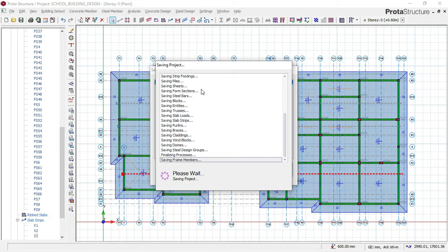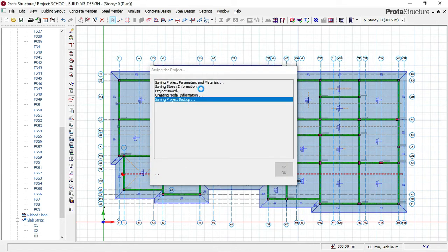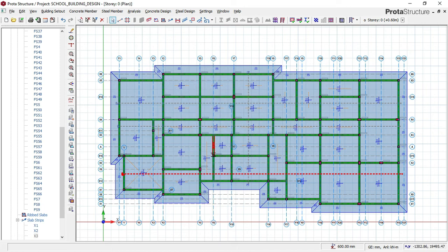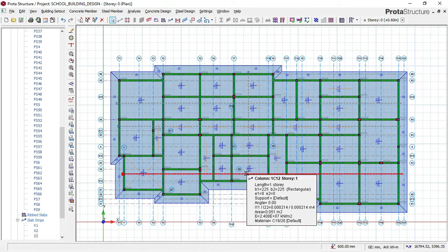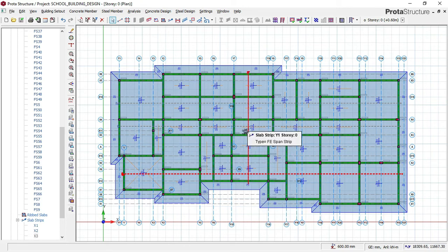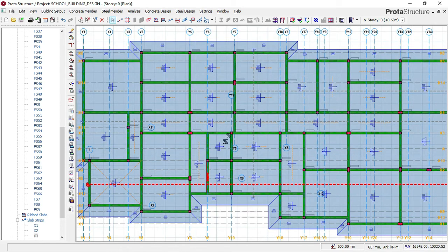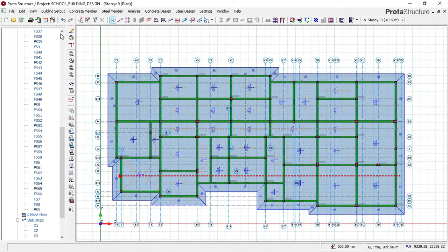If it is for a bigger building, use a Raft foundation. If it is for a very small building, you have to use a wide strip foundation. And if that wide strip fails, then you can now go ahead and use a Raft foundation. Okay, so right now we have cut our strip in X and Y direction, and also we have saved.